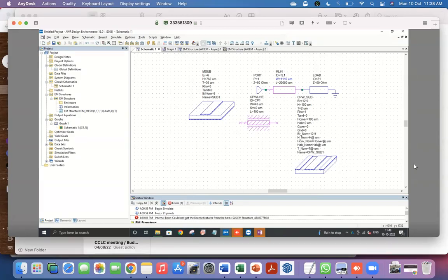We saw in some of the cases where we entered some parameters it didn't like. Now, that usually means that one should not make transmission lines with those dimensions. But if for some reason you are making that as a structure, then you cannot trust the results which these pre-solved models might be giving at those solutions, because they might be outside the range of approximations they have used to compute some closed form formula to extract the properties.